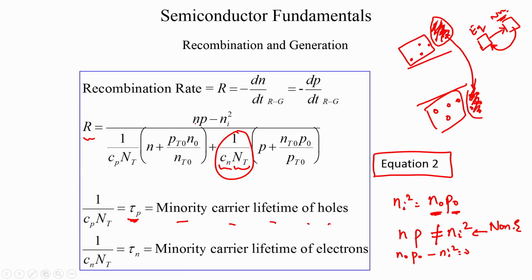What does that mean? It means that if you take a semiconductor that is doped, so let us say a semiconductor is n doped, so it is an n type semiconductor. So, if it is an n type semiconductor, you have a large number of electrons and a small number of holes, the hole population is Ni square by n in equilibrium.